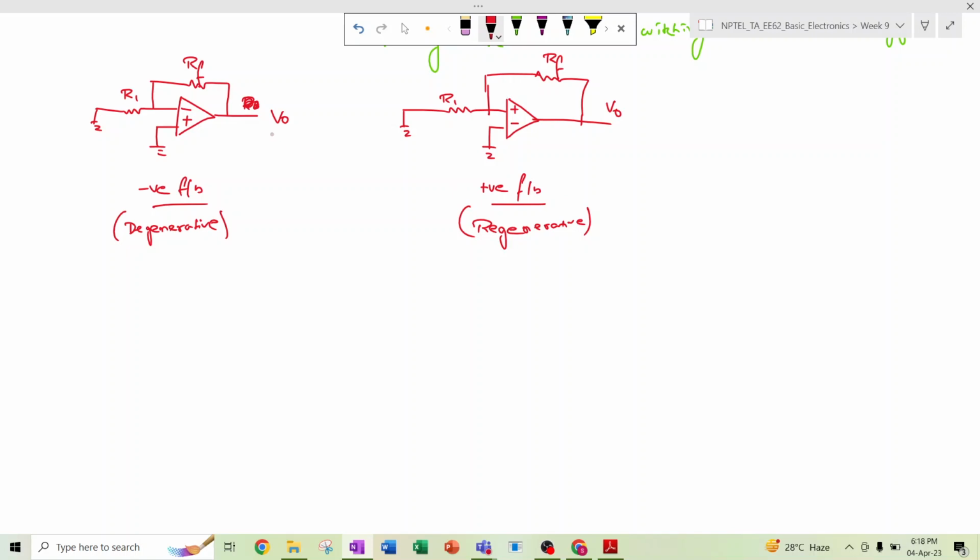The figures show two op-amps, one connected in negative feedback configuration and the other connected in positive feedback condition. The similarity of these two circuits is that in both cases there is no external input excitation, right? So basically we have grounded both the positive terminal and the negative terminal. Both the op-amps are ideal. You consider both op-amps as ideal with infinite loop gain, that is, the open loop gain is infinite, and also there is no sink current, that means no current can flow into the op-amp.